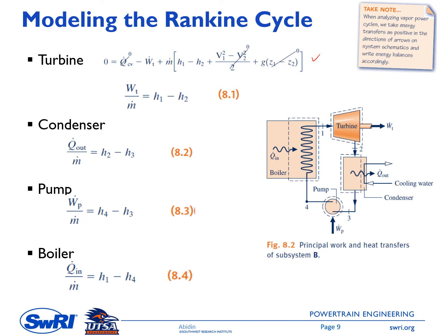The turbine is treated as an open system, or control volume system, so the volume is constant and the mass is allowed to flow across the boundary. In the turbine, usually the process is assumed adiabatic, so in this case, Q is 0.